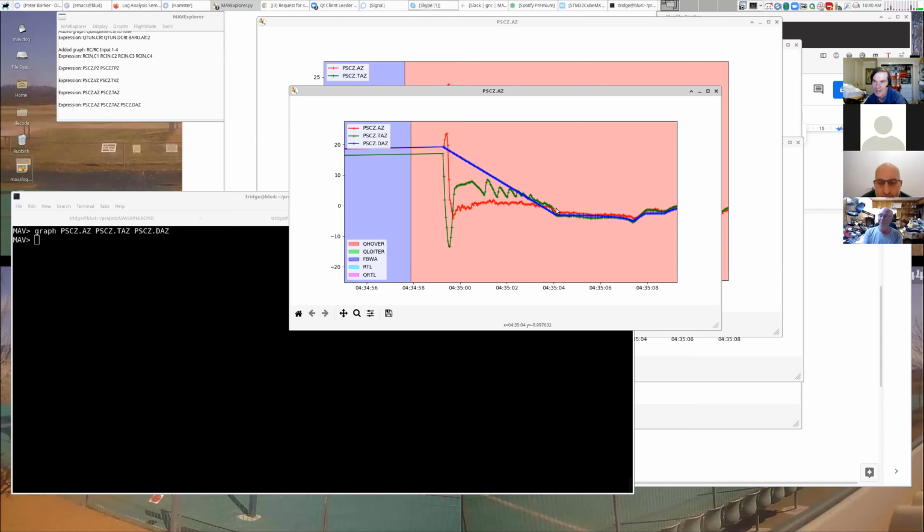So this is the part that prevents it from doing sudden jerks vertically, right? So this is what prevents it doing very, very sudden vertical controls where you go whoosh, whoosh, like that. But it gets initialized here at the start to the actual vertical acceleration at the start. So what's happening is we're coming along, we put the nose up. That initial nose up leads to a very high vertical acceleration, because if you tip the nose up to 45 degrees when you're going along at 80 kilometers an hour, you are going to accelerate up vertically a lot. And then it hands over to the vertical controller and it initializes the vertical controller. That's this point here, initializes the vertical controller with our current vertical acceleration, which is this 2G.